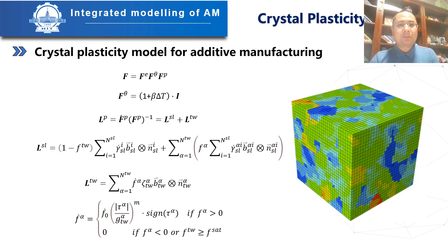Additionally, we have integrated a crystal plasticity model to manage stress-strain evolution through the additive manufacturing process and to predict the mechanical property of the printed components. Within the crystal plasticity simulation, we assign a small elastic modulus to the liquid and gas phases. All model parameters are set to depend on temperature variations. Our model incorporates various factors including thermal expansion, phase transformation, such as twinning and martensitic transformation, as well as dislocation slip.